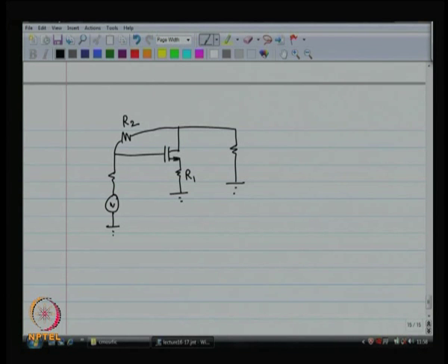A 1 gigahertz oscilloscope does not process only signals at 1 gigahertz, it has to process all frequencies between 0 and 1 gigahertz, right. So, it is a wideband system, and this particular shunt series amplifier, for example, is used a lot of times as the input front end for an oscilloscope.